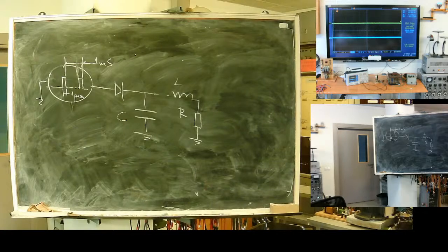They are hidden under the tangent delta idea. For an ideal capacitor, current and voltage form an ideal 90 degrees. The deviation between them makes active losses in insulation.